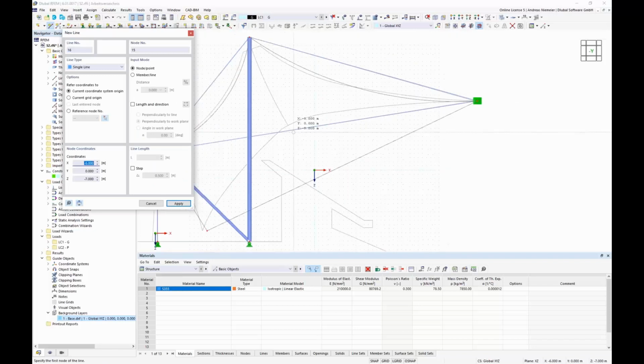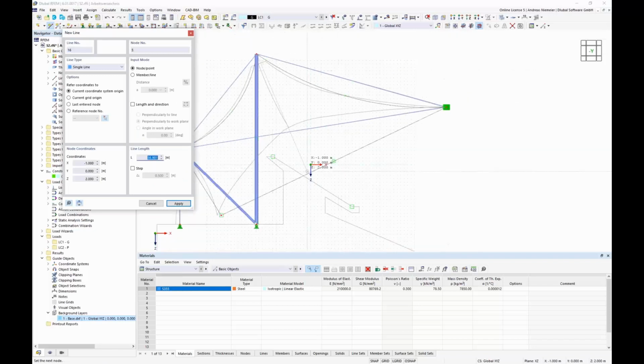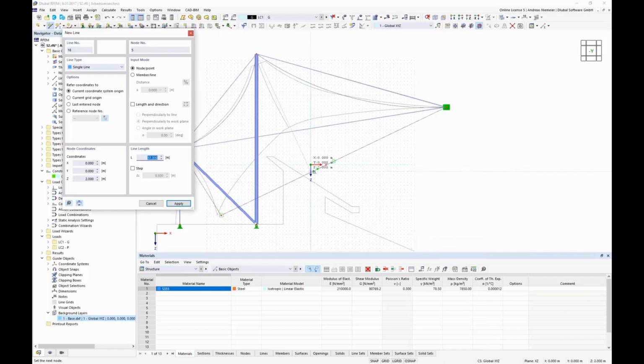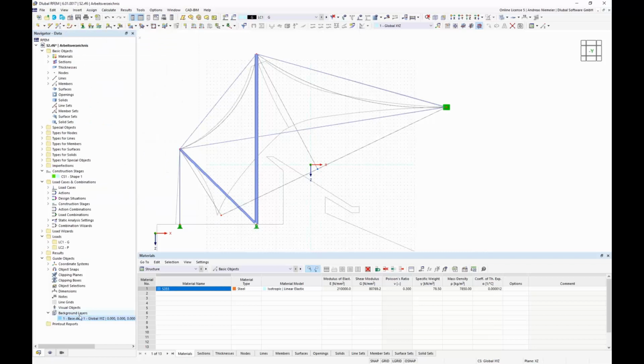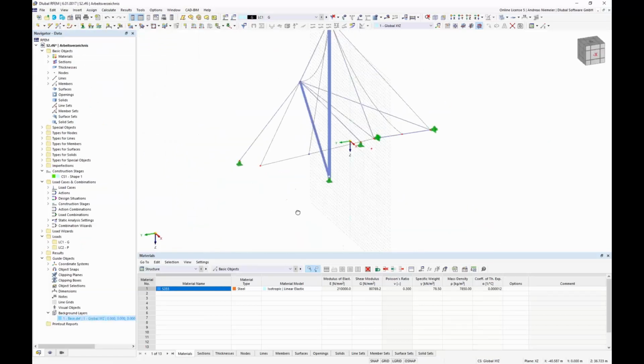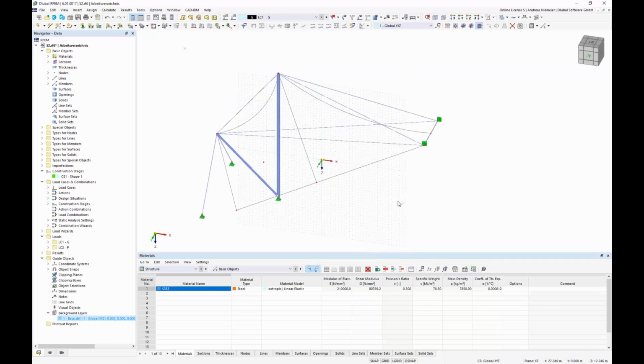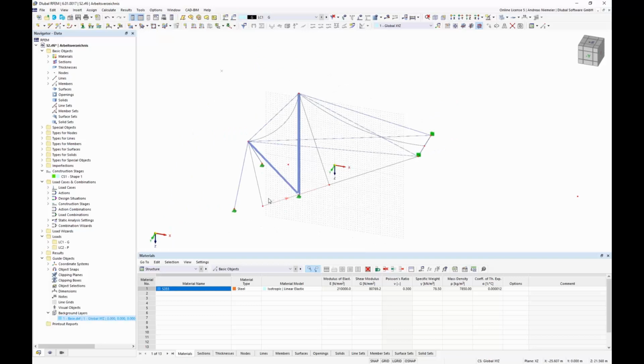We need here a splice cable. So also define here a splice. And if we want to define it here on the perpendicular point, so we can do like this. Now we can deactivate this shape. You see we specified the boundaries for the membrane and can support now cables on these boundaries.